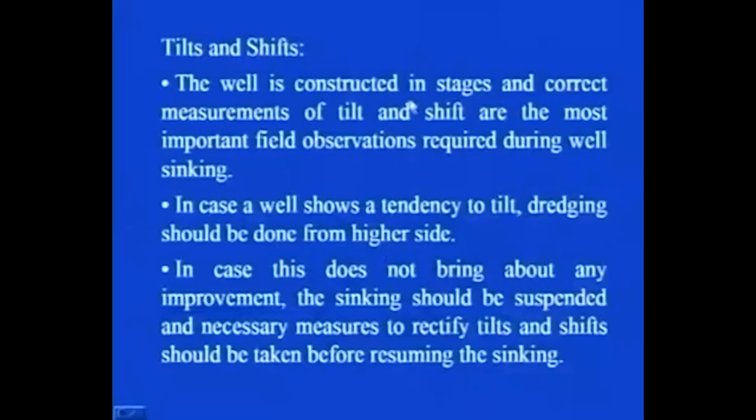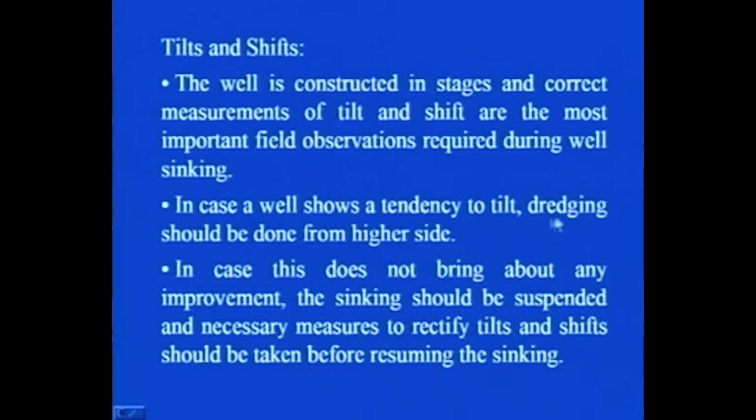The well is constructed in stages, and correct measurements of tilt and shift are the most important field observations which are required during the sinking of the well. Because without the correct measurement of tilt and shift, you really will not be able to know whether it is going beyond the permissible limit or whether it is within that. If it is within that, then there is no problem, but it should not be more than the permissible limit. In case a well shows a tendency to tilt, dredging should be done from the higher side.